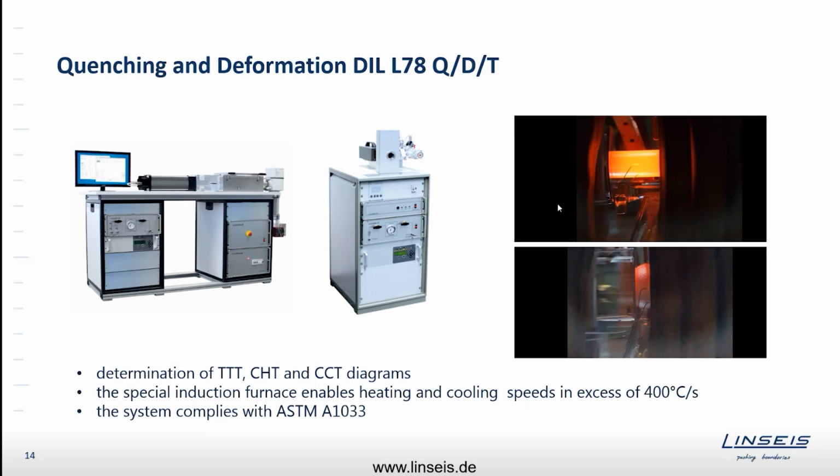The cooling is achieved by pushing expanding cooled helium gas through this coil. So this hollow coil has these little black holes here where the helium gas can be brought to the sample quite quickly. So you can really heat and cool the sample within seconds. In case of the deformation setup, there's an actor, and the actor can actively deform with some kilonewtons. So if you can heat it up fast, you can also apply very high forces to simulate a forging process, simulate a mechanical process quite properly.